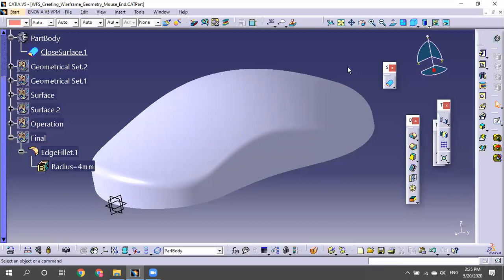On top of surfaces, I do some operations within the surfaces so that I attain my final styling of a product. That's what the edge fillet you can see. And this edge fillet, finally, I'm going to convert into a solid of thickness, whatever it could be. Okay. So this is the entire storytelling you should tell if anybody asks you.